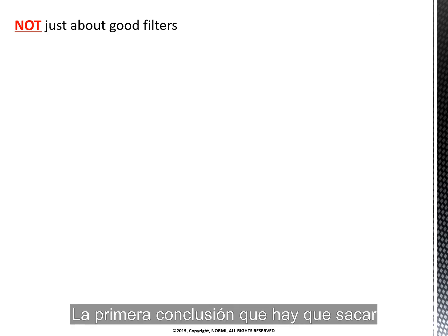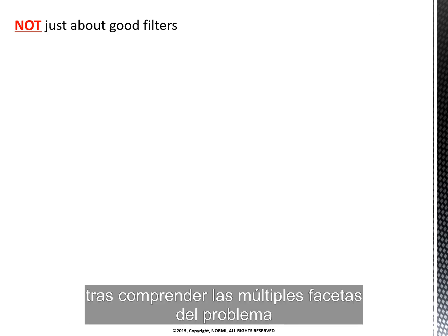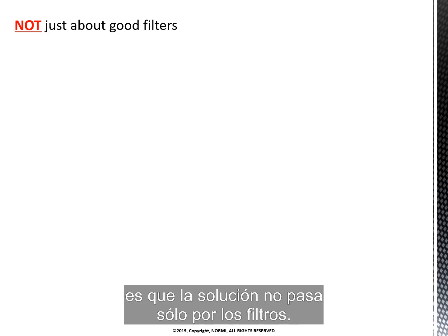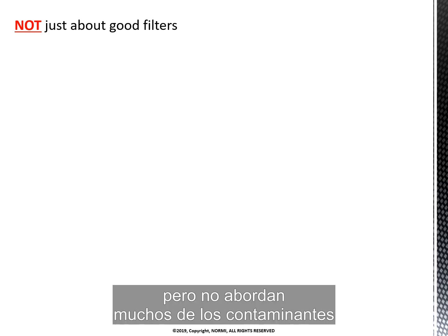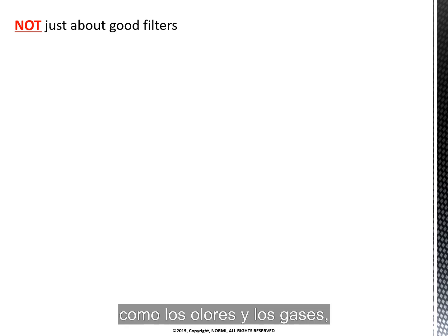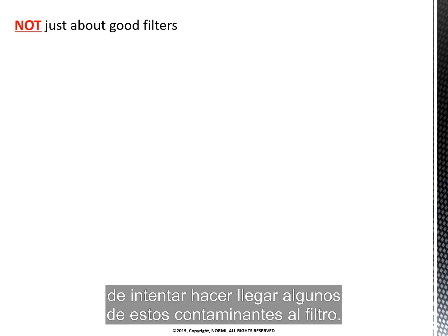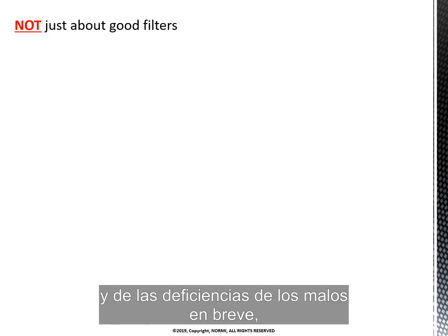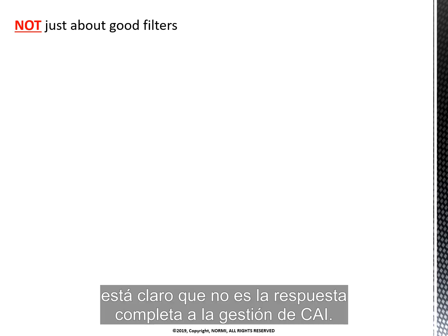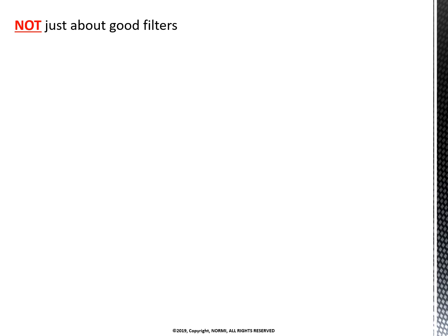So the first conclusion that should be drawn after understanding the many facets of the problem is that the solution is not just about filters. Filters play a very big part in resolving many issues, but they certainly don't address many of the pollutants like odors and gases, and they are restricted by the difficulty of trying to get some of these pollutants to the filter. We'll talk about the value of good filters and the shortcomings of bad ones shortly, but even before that discussion, it's clear that it's not the whole answer to IAQ management.